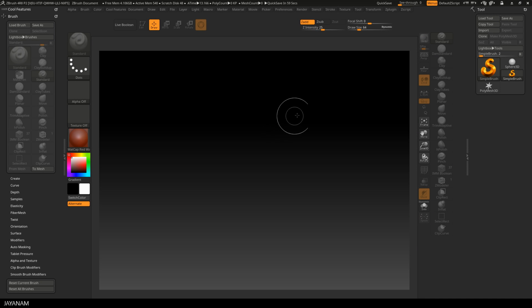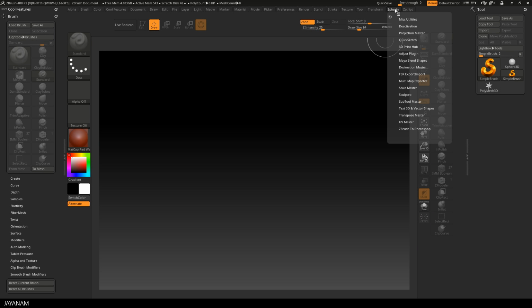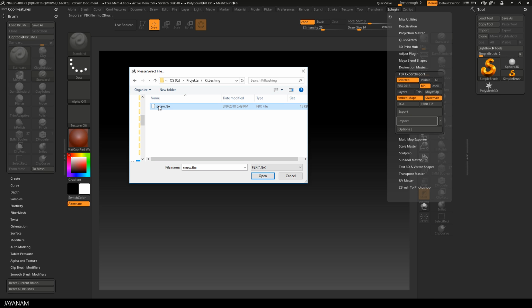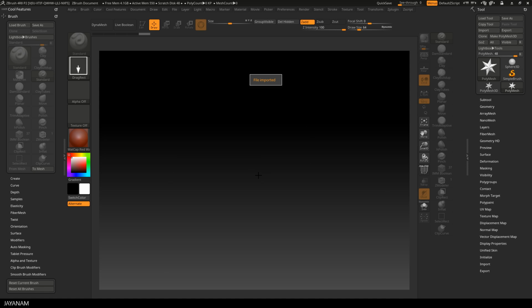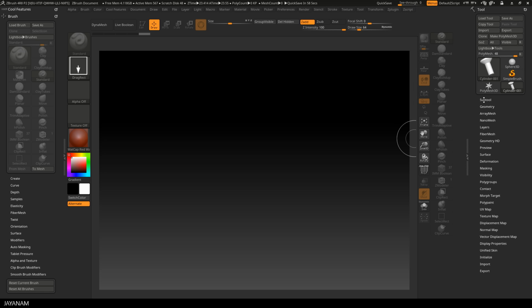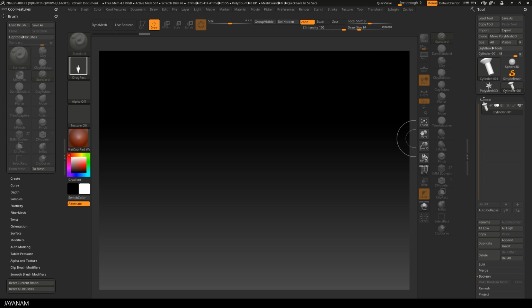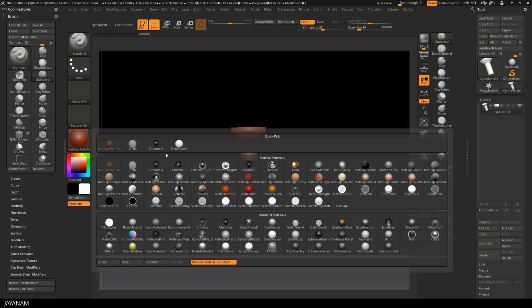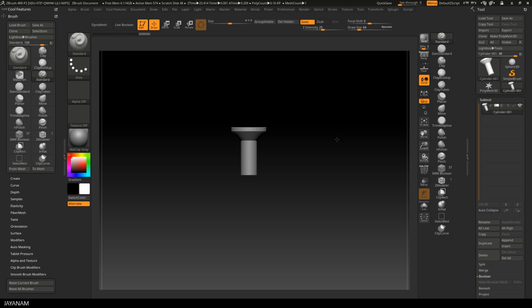Okay, then I open ZBrush 2021 R8 and import the FBX with the FBX Importer that you find under Zplugin. Now the FBX is imported as a new tool and I drag it onto the screen and immediately choose Edit, or you can also press the T key. Okay, then I change to a gray MatCap.